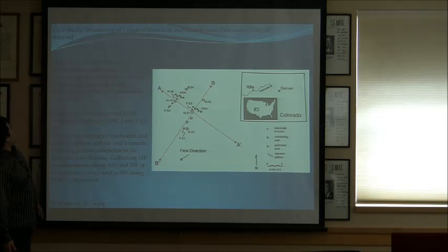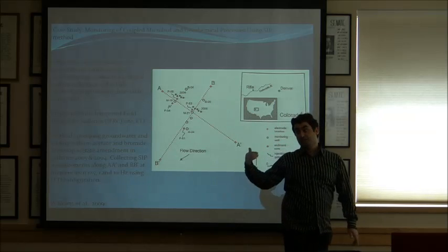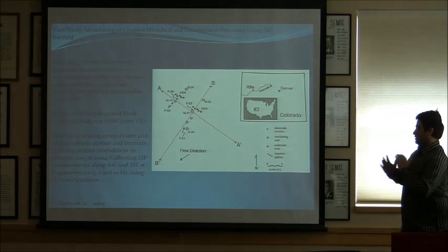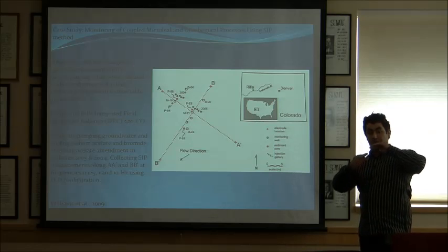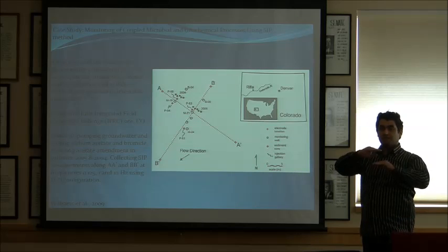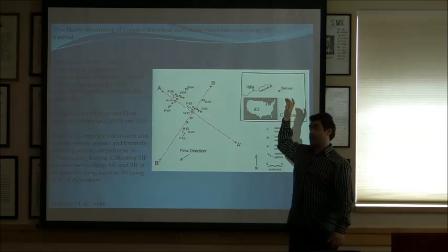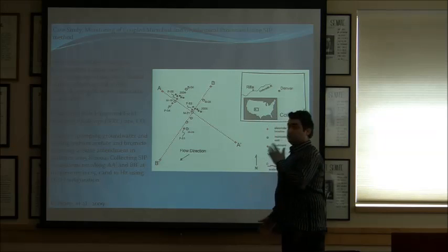And their big question is, can we predict the groundwater geochemistry and the mineral precipitation using this type of measurement? This type of measurement is spectral-induced polarization, and the difference between it and, for example, resistivity is that resistivity is sensitive to the bulk volume, but this is sensitive only to the interface between the fluid, if you have fluid, and the grain. So using this measurement, you are focused on the pore space. In other words, you can differentiate pore space that has mineral in it from pore space that has fluid in it. This is very useful.